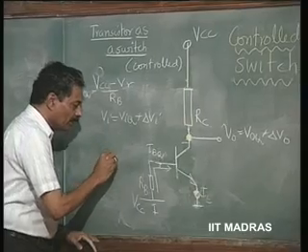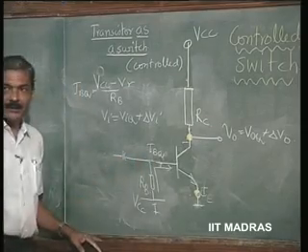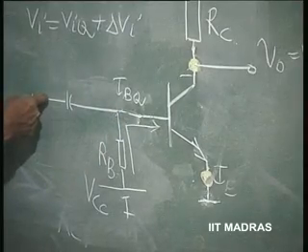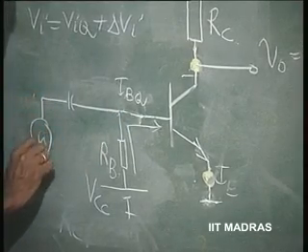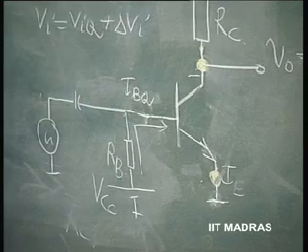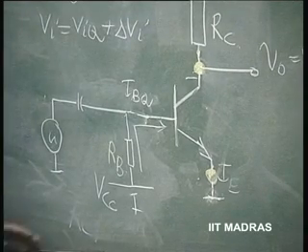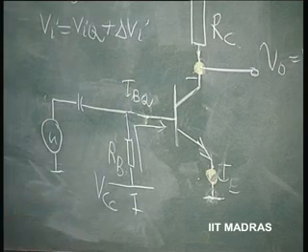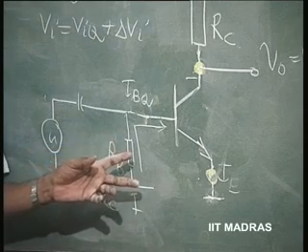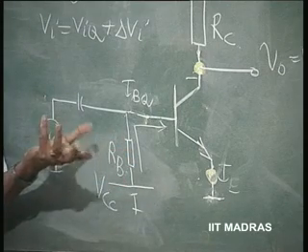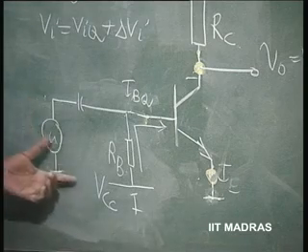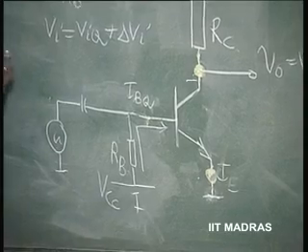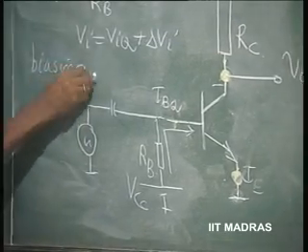then I can superimpose an AC by using capacitive coupling, right. This capacitor will block the DC and will couple the AC. So, this is the advantage of using current biasing instead of voltage biasing. Instead of using a battery whose value is VBEQ, and what is the order of VBEQ? Of the order 0.5 to 0.6, I can use this current biasing. We will discuss further about this in the next class. Biasing a transistor.